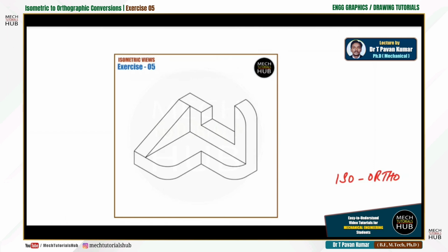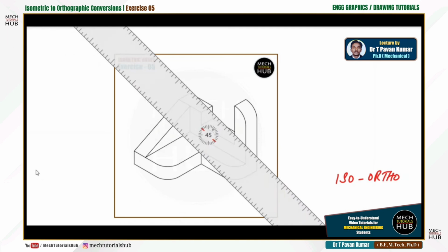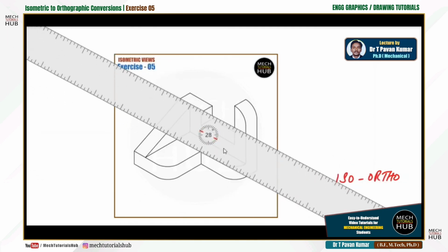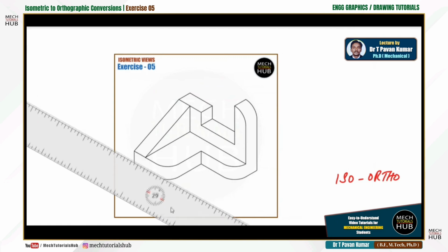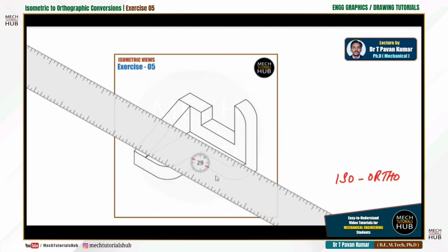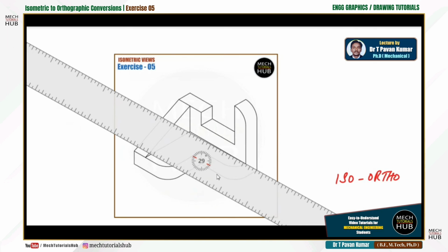Now I'll just consider a 2H pencil or a light color gray pen I have taken, and now by using this scale I'll show you in a simple way how exactly you can represent. I'm aligning the scale with this horizontal. Now all horizontals are parallel, 30 degrees.